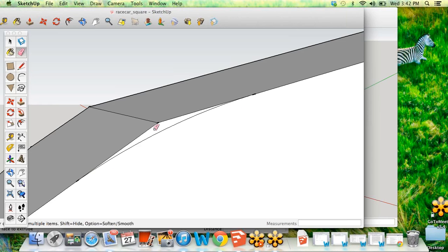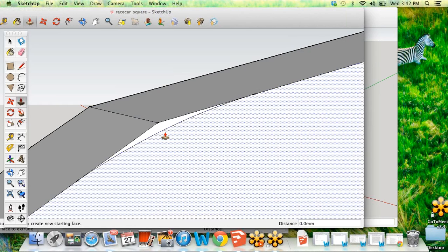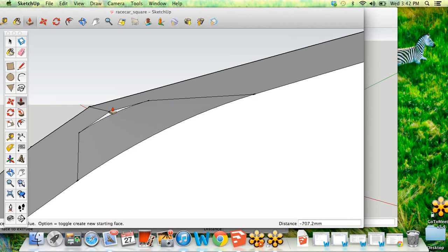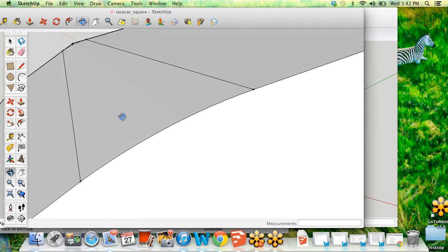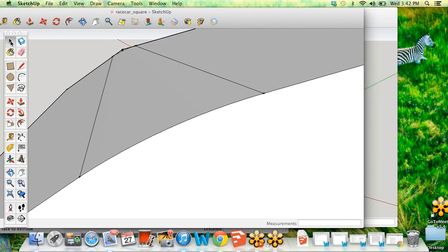Now that I have this tangent arc drawn, again, just using this arc tool and drawing my start and my finish and getting either that purple or that blue curve, I can use my push-pull tool, select that face, and punch it out. You can see it's almost like we're carving away that sharp corner. Try that again. Okay, and I'm going to select that edge there.